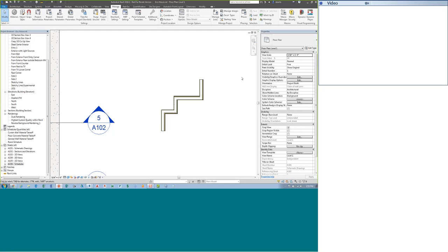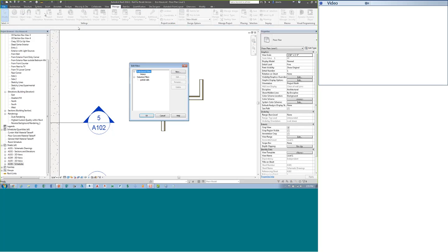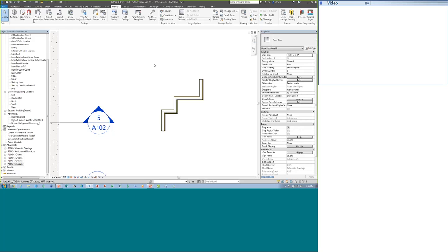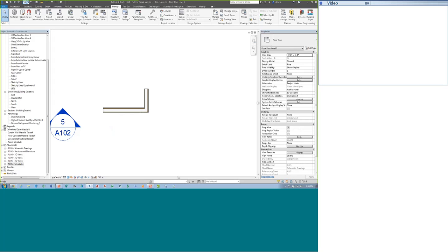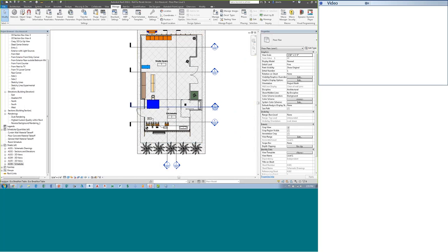Okay. Command number 4, undo. I love undo because I mess up a lot. So I can just do Control-Z, and it goes back to previous. I could also use this arrow key and click, and each time I click, it undoes each step of the way. I can also use the little black arrow to the right of that, and it gives you a running history of all the commands that you've done. So the more that I highlight, the more the software will go backward.